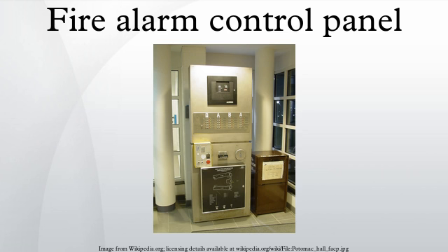Monitoring. In nearly every state in the USA, the International Building Code requires fire alarm and sprinkler systems to be monitored by an approved supervising station. A fire alarm system consists of a computer-based control connected to a central station. The majority of fire alarm systems installed in the USA are monitored by a UL-listed or FM Global approved supervising station. These systems will generally have a top-level map of the entire site, with various building levels displayed. The user can progress through the different stages.